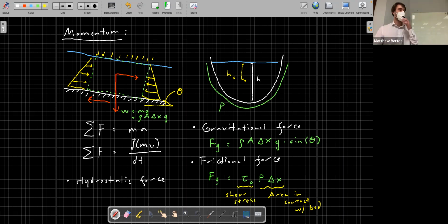Okay, and the hydrostatic force is equal to the pressure times the area, right? Specifically the pressure at the centroid of the fluid times the area of the cross section. Okay, so we can express that as our hydrostatic force FH is equal to, we're interested in, the pressure applied at this upstream face minus the pressure applied at this downstream face here.